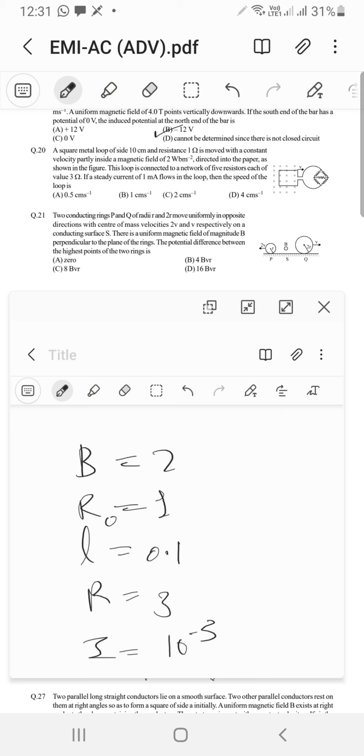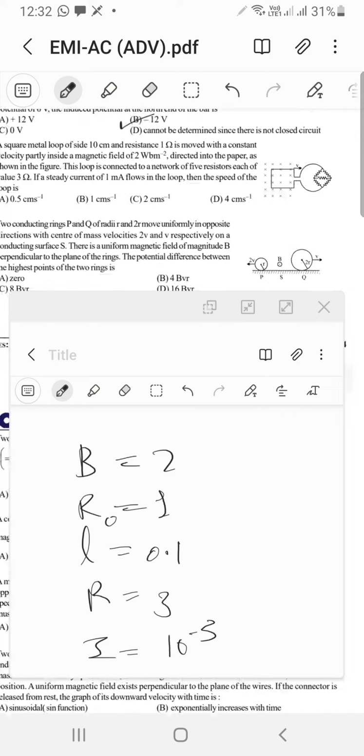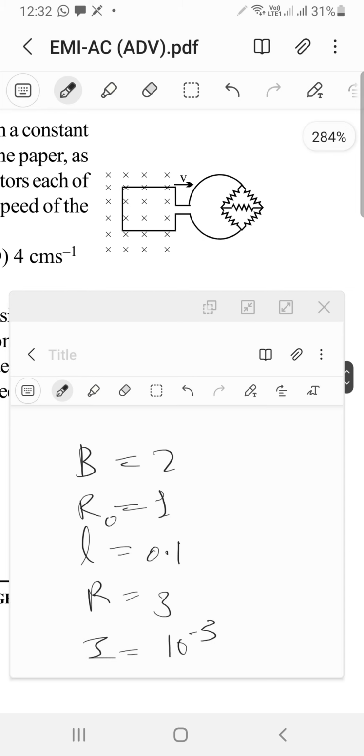all right, so you know what the current through this thing is. Wow, this is complicated. Come on, think about it. Wait a second, we said that all of these resistors are of 3, right? Hey, that's a balanced Wheatstone bridge, so just remove this thing.